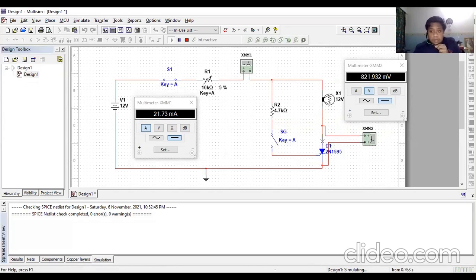This is because the thyristor does not receive enough current, so it will close the circuit back. Okay, now here we can see the holding current of the thyristor. That means at this value, the thyristor will deactivate.